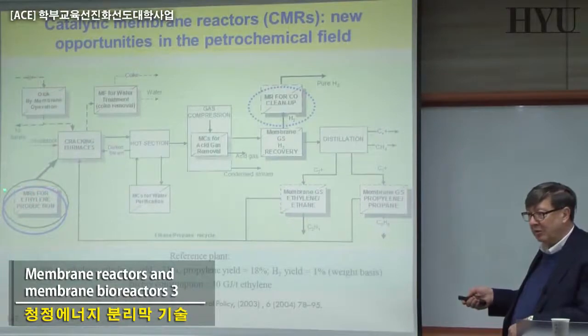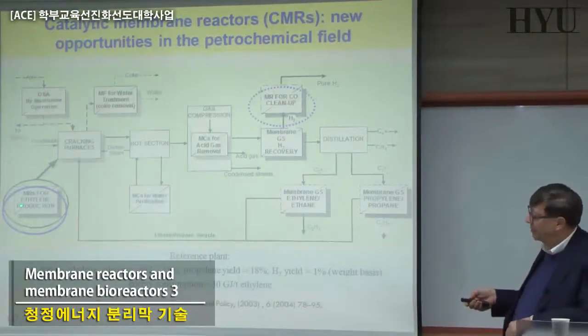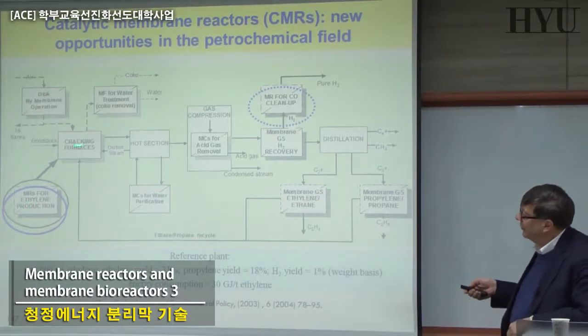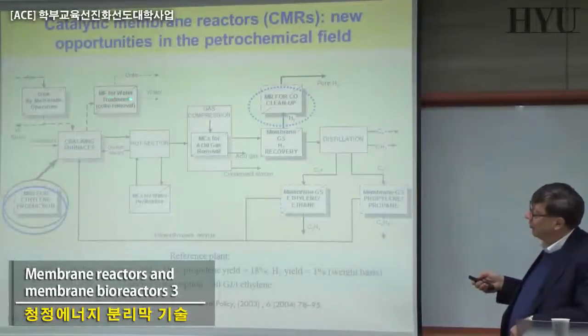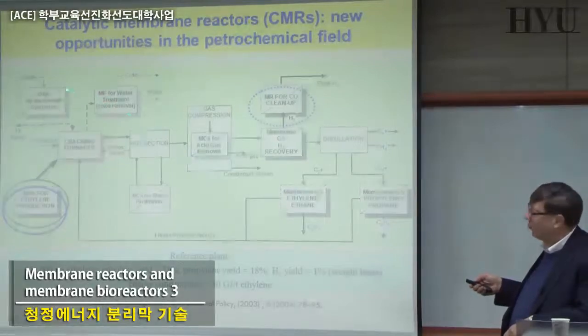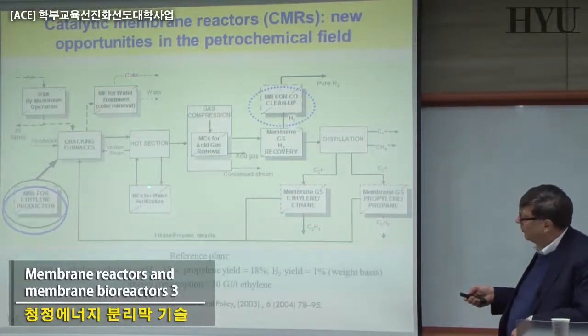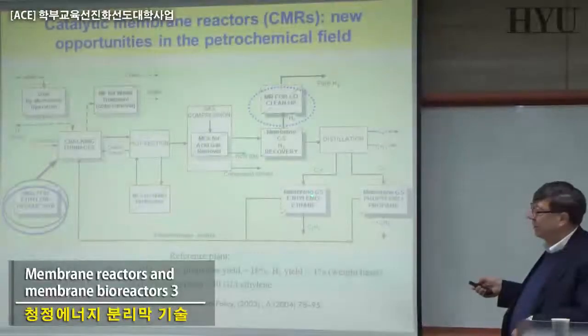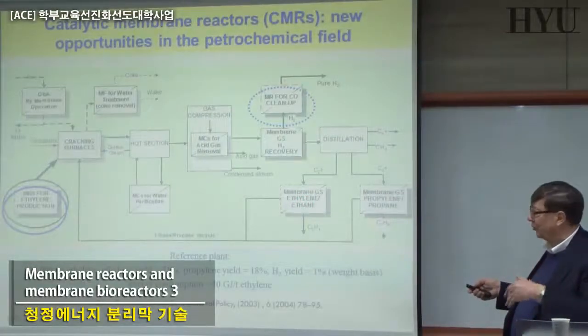You enter with your gas, methane, for example, and you start to produce ethylene, and after that everything will be just membrane filtration, microfiltration for some cleaning, if there is some coke removal, etc. And there are again membrane contactors for removal of acid gas, membrane contactors for water purification. Here are gas separation units for the separation of the aromatics, the saturated ethane, and ethylene.